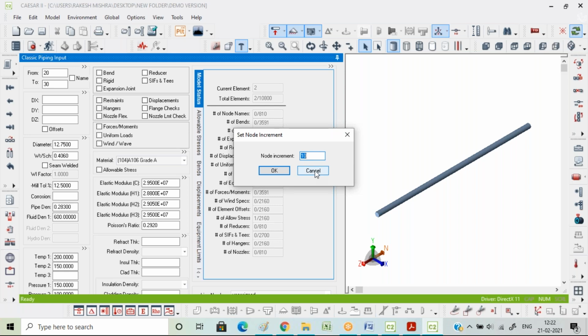My personal preference is to always use a multiple of 10 for nodes, and a multiple of 5 for supports. So whatever number ending in 5 is coming, like 15, 25, 35, 45, I'm very clear in my report that this particular node point is indicating a support.